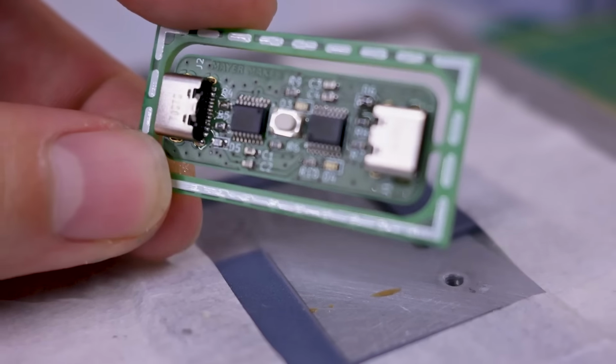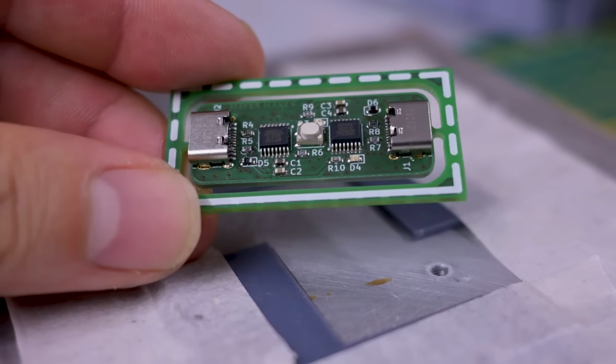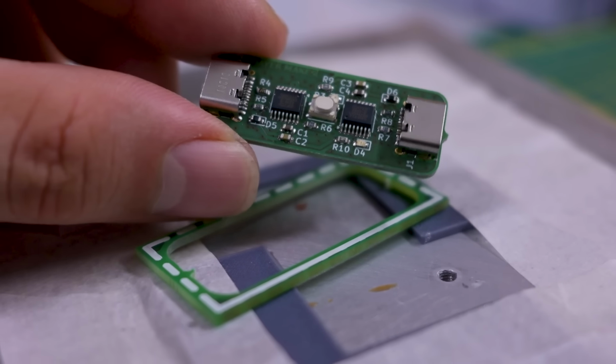If you use USB-C ports that are only USB 2.0 enabled, like here, because there's no point in USB 3 because the chips don't support it, then you can basically just look at it closely and see if there are any bridges. Make sure those are gone before you power it up the first time, so you don't short out your device.